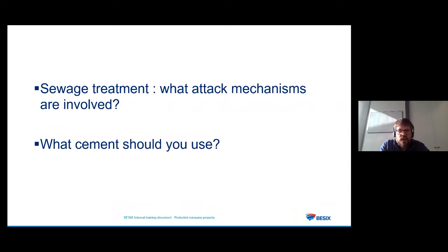Just for information, in terms of carbonation, CEM1 is better. But usually, cement type 1 is better than 3, you mean? Yeah, for carbonation only. Usually CEM1 is better in terms of durability only for carbonation, but CEM1 is better to go faster, to cast concrete during the winter and things like this. Okay, thank you. But it's bad for carbon footprint also.